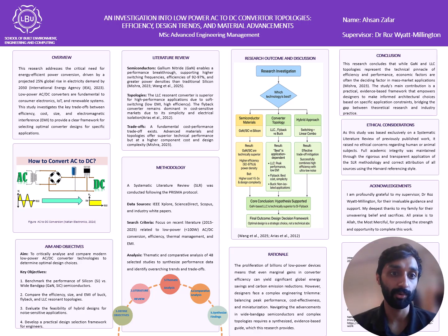If we can talk about the discussion, we can discuss the results. These results highlight several important trade-offs. First of all, efficiency versus cost. GaN plus LLC converters are the most efficient, but they're expensive. Flyback converters are less efficient, but still dominate the low-cost consumer market.